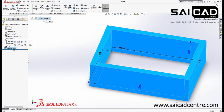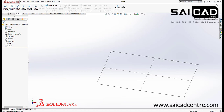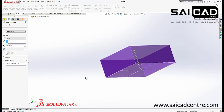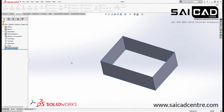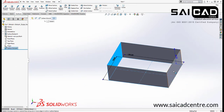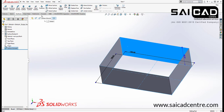If you want to create a surface, then you have to go to the surface tools, use the extrude from here and select the sketch, and you will get a shape like that. You will have the similar options here, just one option added, that will be cap ends, and one option removed, that will be the thin feature. If you click OK, you will get a surface body from here. So you will get four different surfaces right here. You can choose the surface, you can apply all the commands, you can manipulate these bodies from right here.